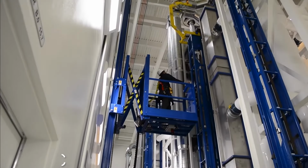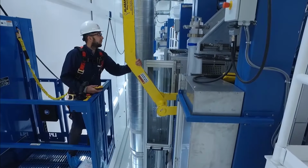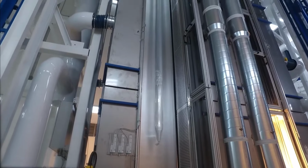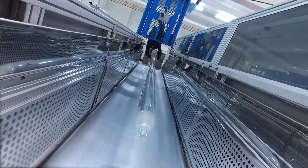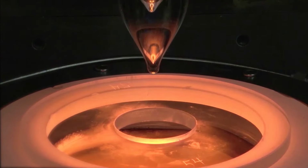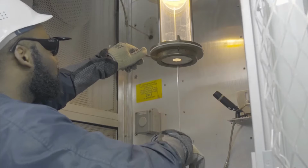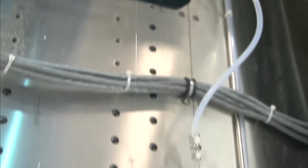Upon heating at 1900 degrees Celsius, the tip melts and gravity drags it into free fall. Following that, a narrow strand of 125 microns in diameter is drawn. A diameter gauge system using laser technology assures that every segment of the optical fiber has the same specified size. The optical fiber is next passed through a die, which provides a protective coating that makes it durable and simple to handle. It can now be coiled onto a drum.